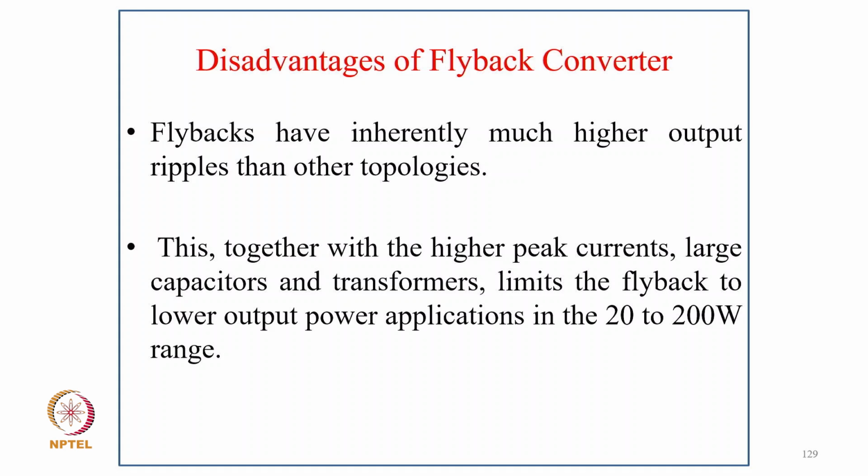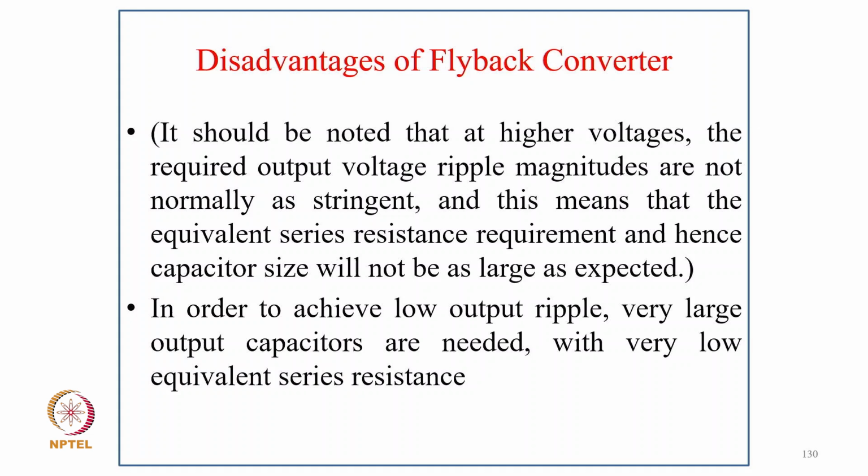The flyback converters have inherently much higher output ripple than the other topologies. So this, together with the higher peak current, large capacitors and transformer, limits the flyback to lower output applications in the 20 watt to 200 watt range.